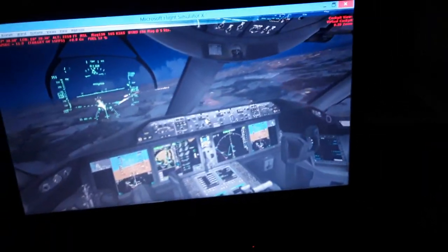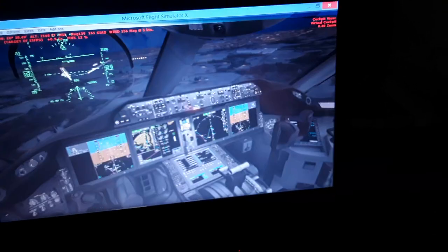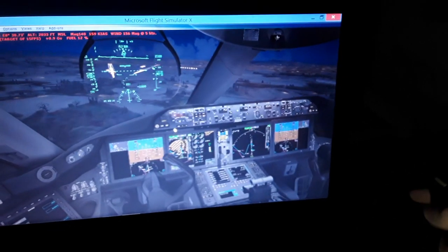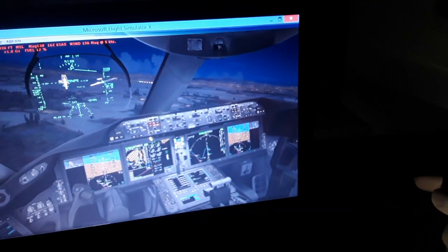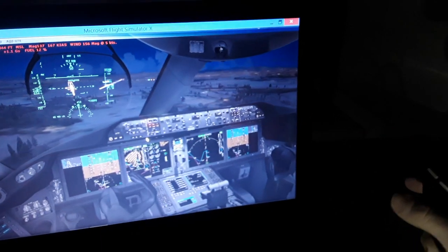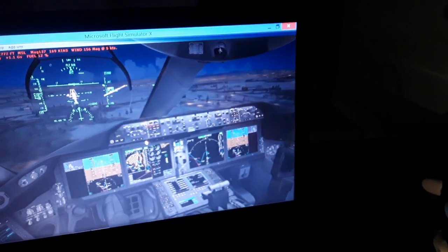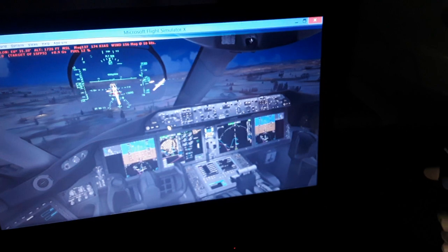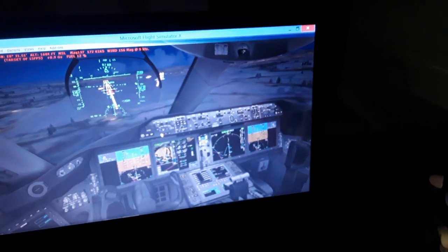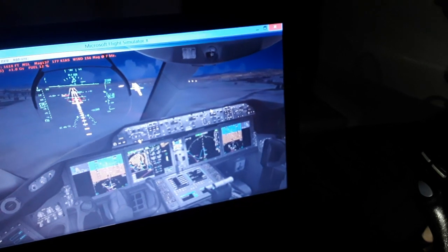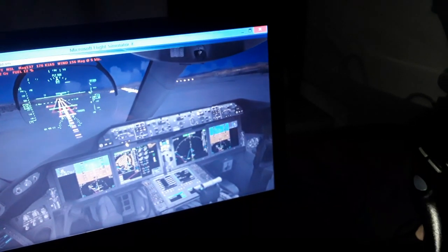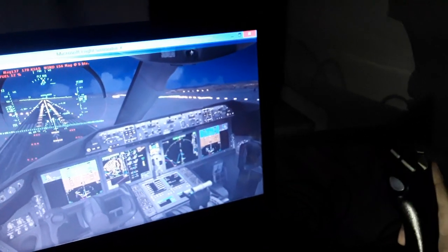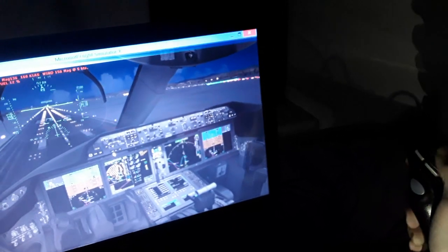So again, some wind gusts over here, side wind. Use a little bit more engine thrust over here. So we're gonna make it. Wind gust, we need to use left rudder now, right rudder sometimes. Also ailerons and spoilers for alignment with the runway position, as you can see. We need to use a little bit more idle as we are approaching for the flare. We align again with the runway center line over here.